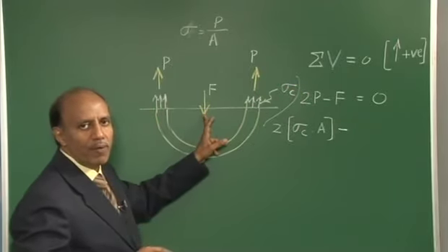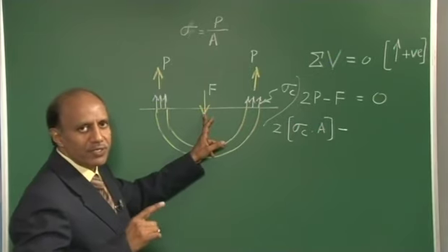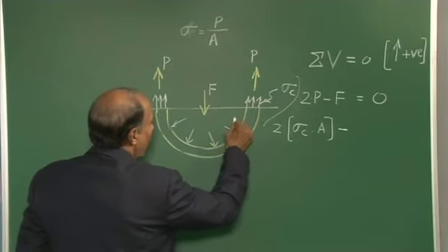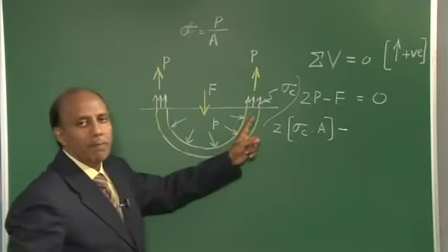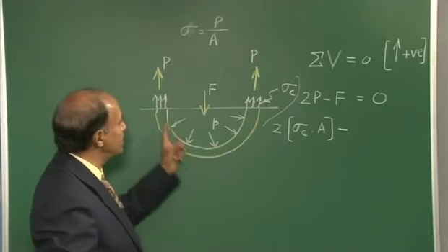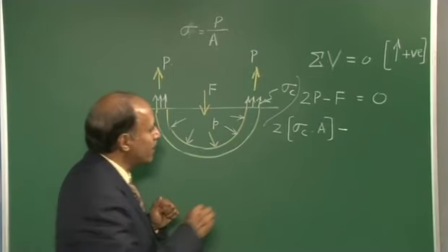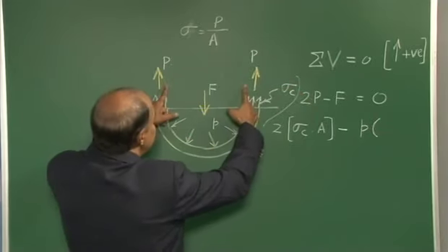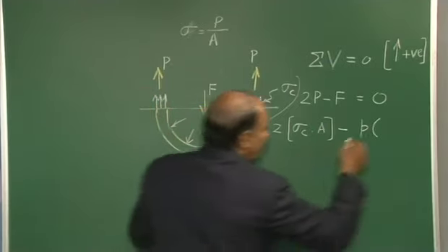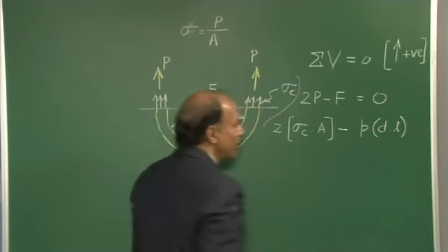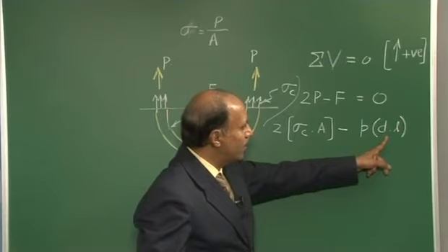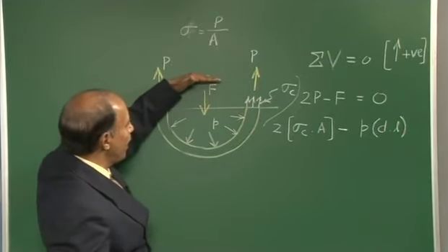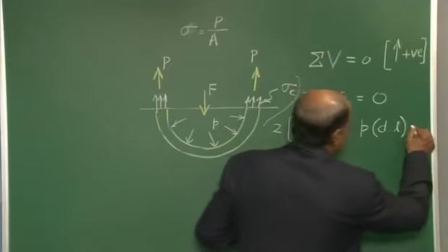We have understood how we normally calculate the bursting force. The bursting force is nothing but the product of the internal pressure P acting inside the cylinder multiplied by the projected area of the curved surface on a horizontal plane. So, it is nothing but the product of the internal pressure P into the projection, which is the internal diameter d into length L, d into L. So, pressure into area will give the bursting force. When you say this area, it is the area of the curved surface on a horizontal plane, that is diameter into L. This has to be 0.